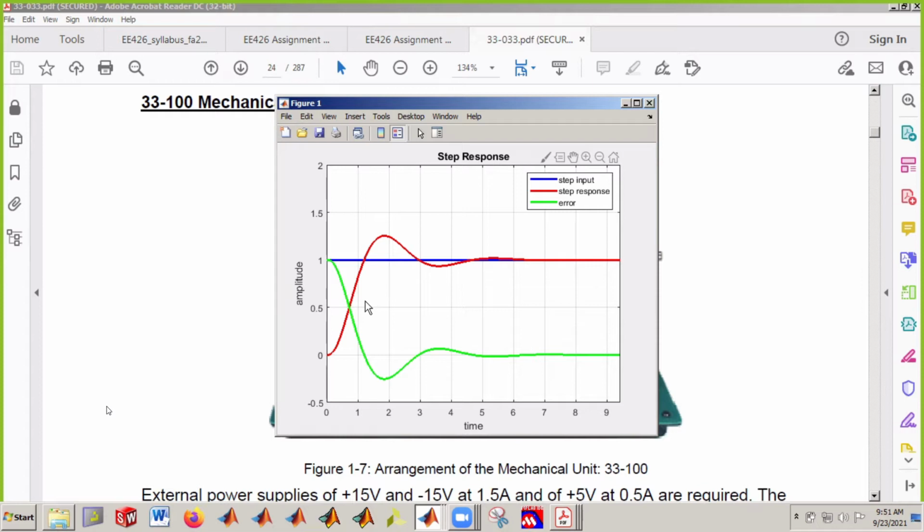So you have to be careful with the gain. Now you may ask yourself, can I fix the value of my KP and do something else so that I can reduce this overshoot without changing the value of the KP, or the proportional controller? And this is where velocity feedback comes in.